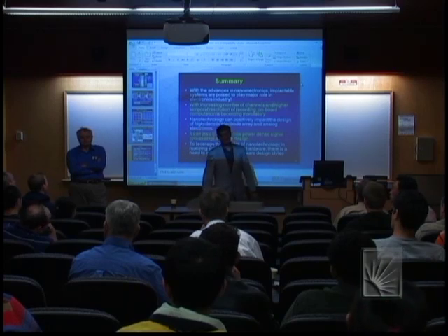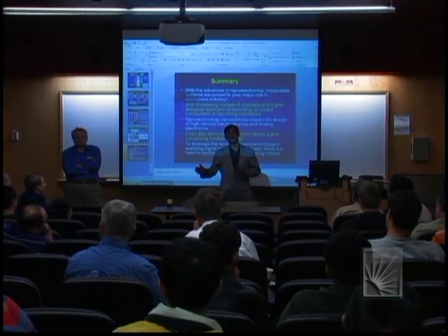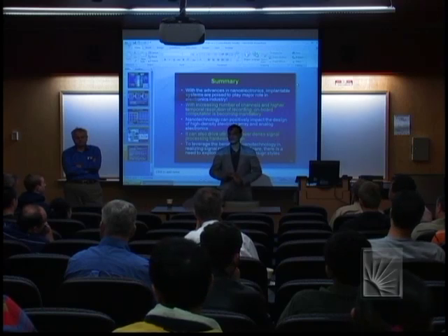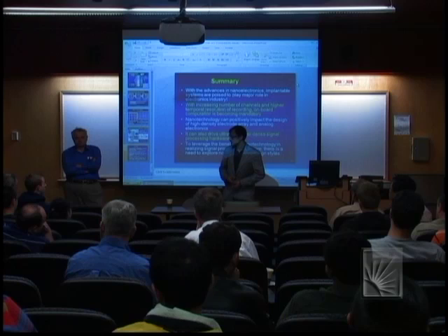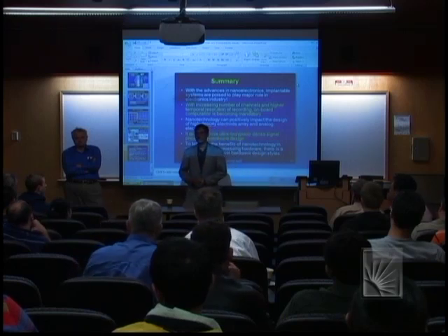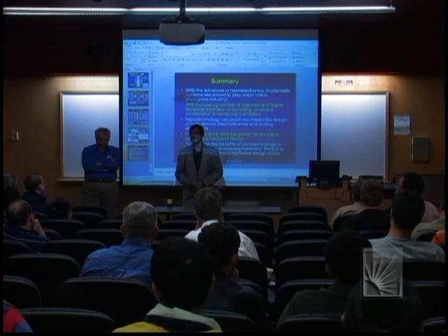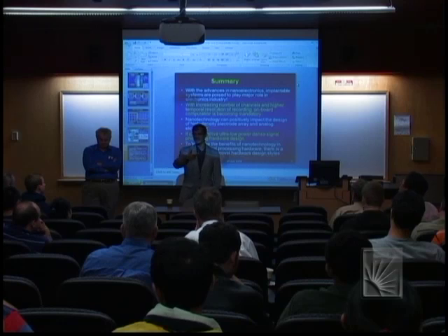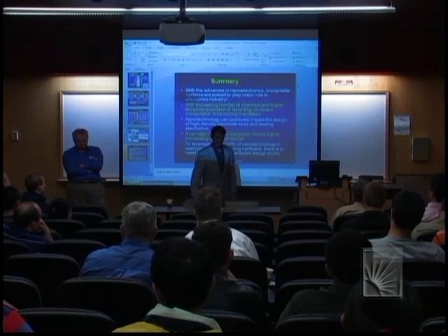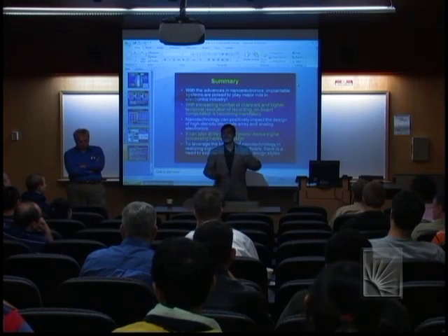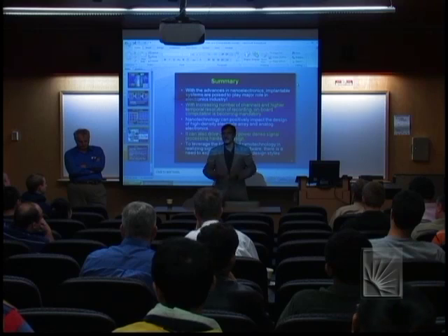The lookup table size, there is a trade-off. If you increase the size of the lookup table, the number of cycles can reduce, but the memory requirement will go up. We have a recent publication which shows that you can exponentially reduce the size of the memory by going to a different memory architecture called content addressable memory. Instead of addressing the lookup table by address index, if you address by the value, you can reduce it significantly. So there are two optimization parameters here: the number of cycles and the memory requirements. You probably cannot optimize both at the same time.